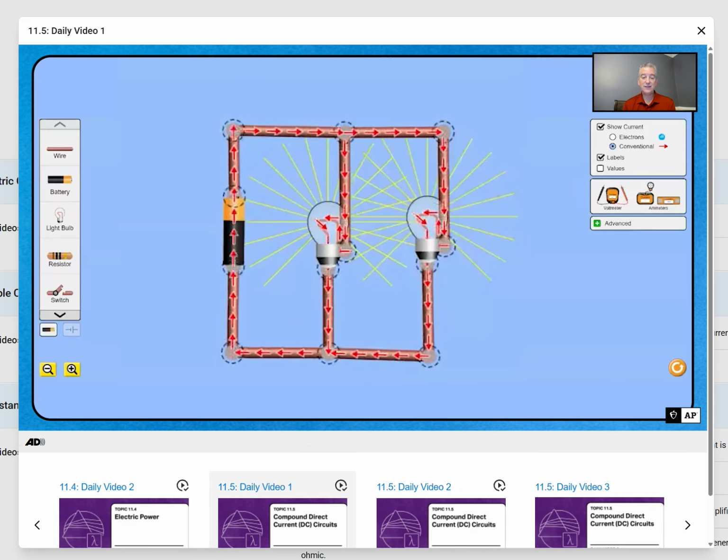In a parallel circuit, they are arranged such that the current has multiple paths to follow through the circuit. When resistors are added in parallel, the resistance of the entire circuit will decrease. The current in each branch will remain the same, but the total current that is moving in the battery will increase. And a break in the circuit will only cause the circuit elements in that branch to stop working, and the rest of the circuit will continue working exactly as before.